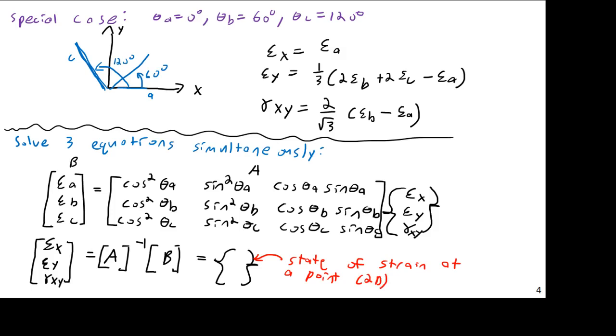We're mainly concerned with 2D because that's how you usually physically measure strain. I mean, yes, there are ways of measuring more three-dimensional strains, involving, say, embedding strain gauges inside the bulk of materials. That's always more difficult. So usually we're concerned with surface strain, two-dimensional strain, where you just slap a strain gauge on the surface of a beam or something like that.